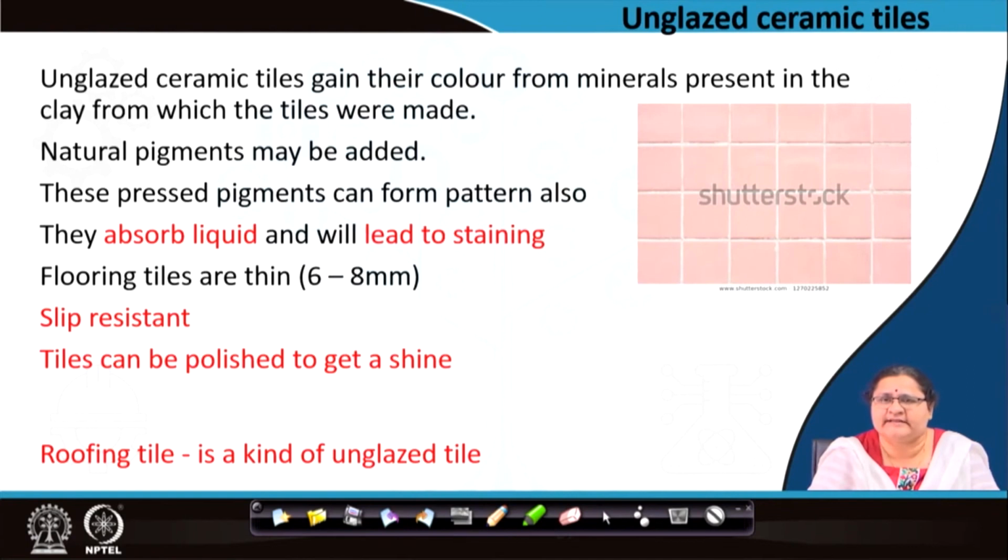You will see the floor tiles are thin, but they are slip resistant because they do not have that glassy, frictionless coating. They are slip resistant, so good for outdoor conditions where water can reach them, but they do not leave the surface slippery. They can be polished also, so you have polished unglazed ceramic tiles. So if you enter into the market, you will see n number of things are there. So how will you as an architect know what to use?